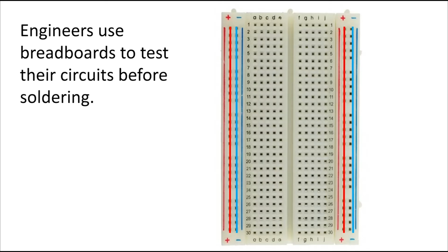The holes in the center of the breadboard are for electrical components like LEDs and resistors. Instead of going vertically, the inside section has wires underneath that connect holes horizontally. When adding things like LEDs, you want to attach each pin of the LED on separate horizontal holes as shown above. If we put them on the same row, no current would flow through it, because electrons would rather flow through the underlying wire, which has less resistance.